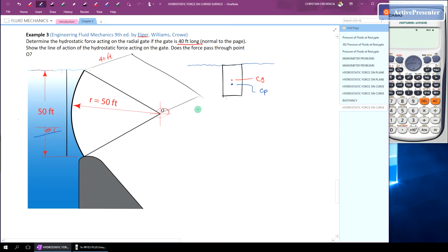Okay, so ang formula natin again is that hydrostatic force on a plane surface is simply equal to unit weight ng liquid, then h bar, and then the area. So this part is actually yung pressure. Pressure multiplied by area is force.